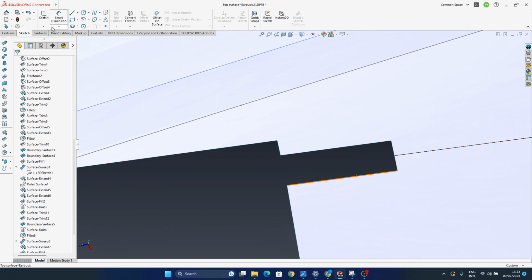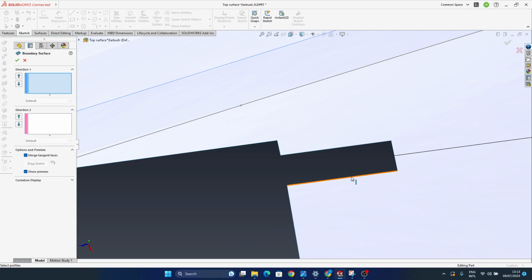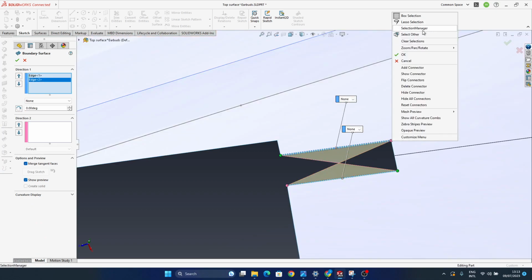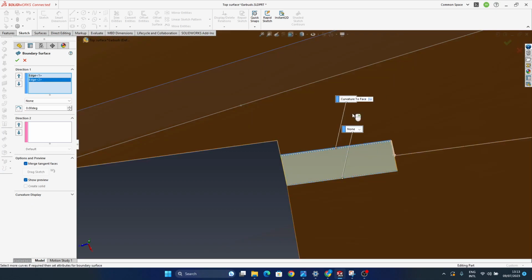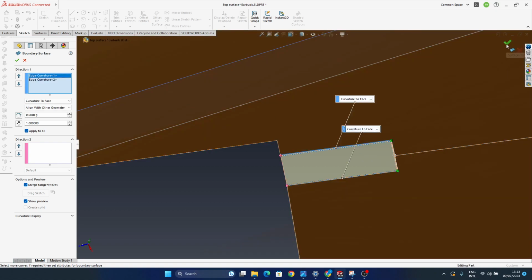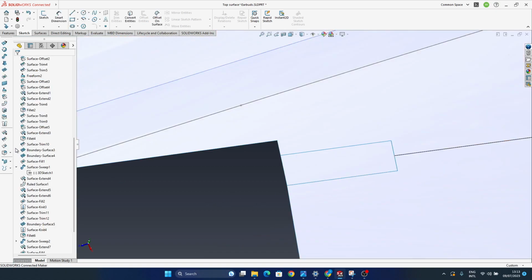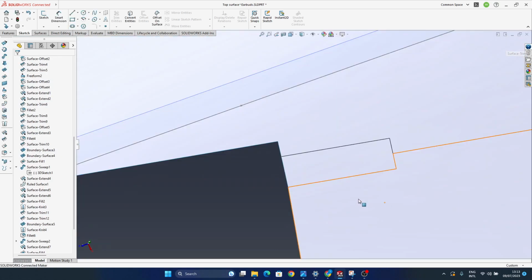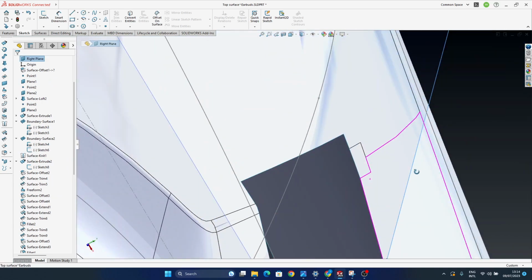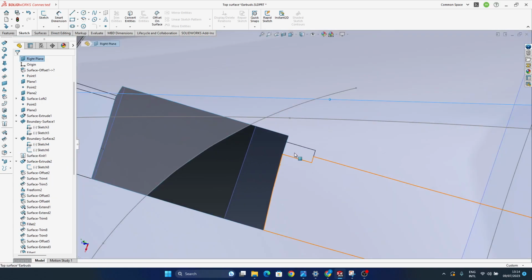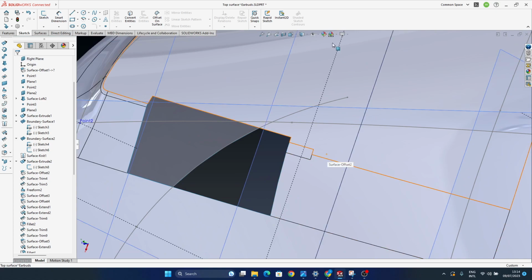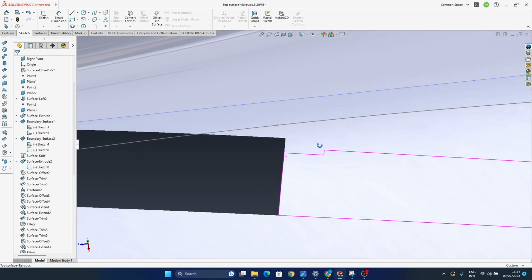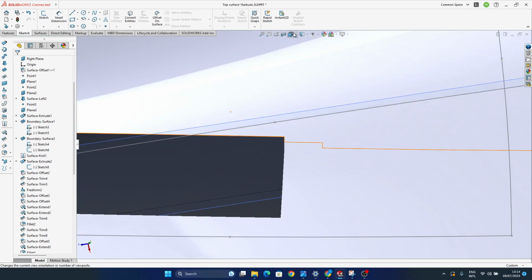Yeah. So I'm going to select this boundary surface between these two, flip connectors both in curvature, and after I'm doing the knit, I should be able to have it done to not have any problems despite I'm having a patch like this in there. And again, the curves and all that shouldn't give me any problems.